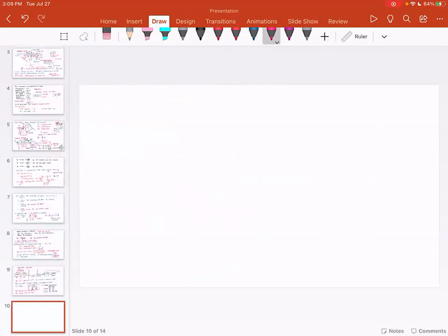And to find the allowable error in action, use table 28.6, where the error in action E is listed as a function of pitch line velocity. So error in action depends upon the pitch line velocity and the type of gears.